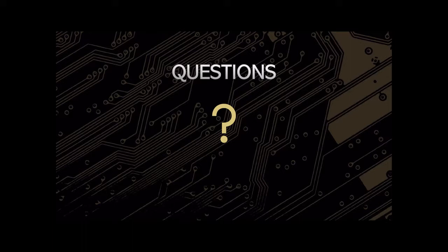As far as the fabrication side, you can add a note in your README file saying something about your solder mask defined pads. That'll stop the hold. But on our side, as far as doing the DFM check, we just have it must be 2 mil bigger kind of thing. And so if it doesn't meet that, that's when we're going to put it on hold. But if it's in the fab note or the README file, it just says, hey, I do have solder mask defined pads, that's going to avoid your hold.